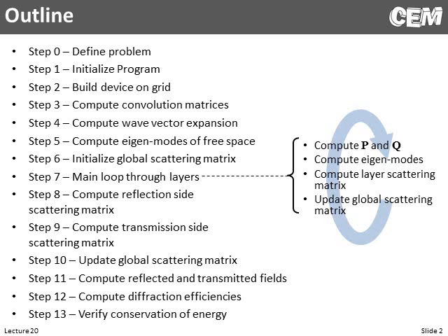Then we enter the code proper for rigorous coupled wave analysis. And we will initialize the MATLAB environment. We will define all of the different material properties, dimensions, source conditions, etc. So all the hard-coded numbers will appear right up front in the code, and then everything else in the code will not be hard-coded. The second step that I like to do is build the device on the grid,